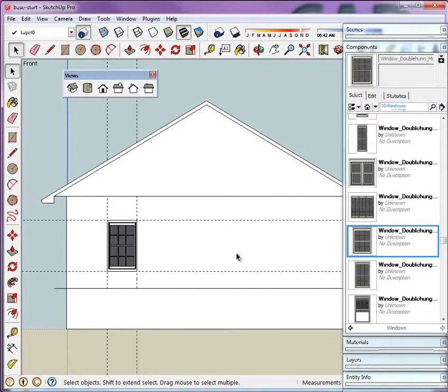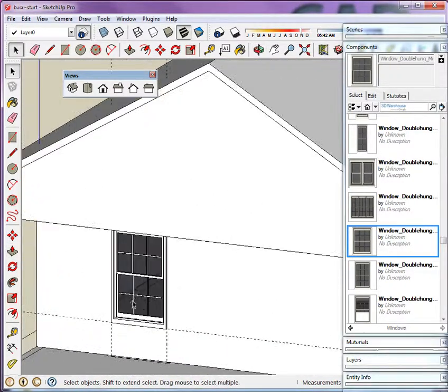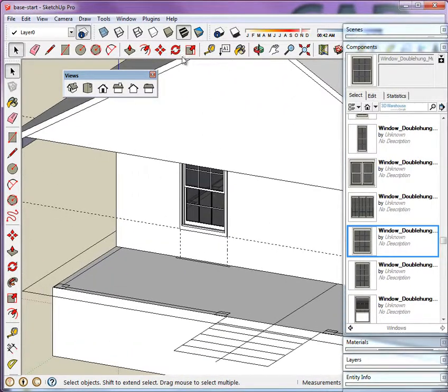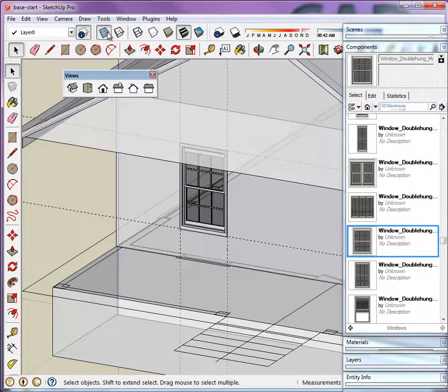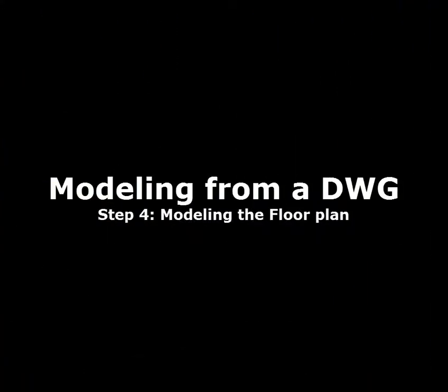And this is how we'll place doors and windows, first by locating them with guides and using our XREF together with X-ray, as you can see up here, to be able to locate the position and size of all our doors and windows. Okay? Next week, what we'll do is we'll continue with modeling, and we'll also take a look at saving each of the views as scenes and then exporting those scenes for use as DWG line work in your original floor plan presentation.